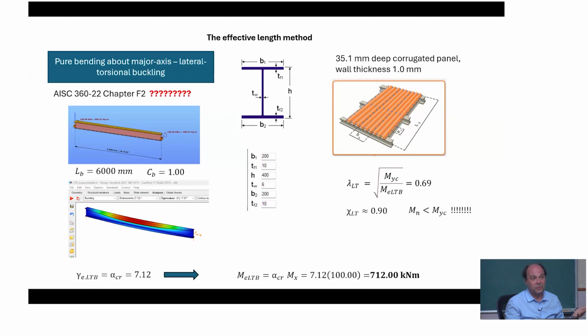Also, in the German standard and in Eurocode, they define the minimum value of S. If the panel is stronger, then you can exclude LTB in your calculations. If it is less, then no one tells you what to do, probably nothing. Then people either select a stronger panel or they disregard the effect in the calculation.